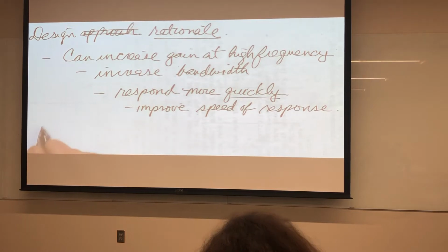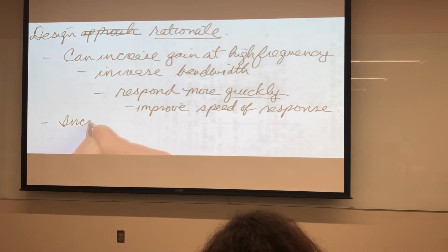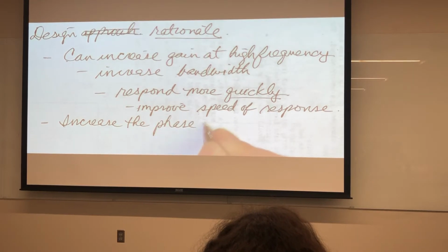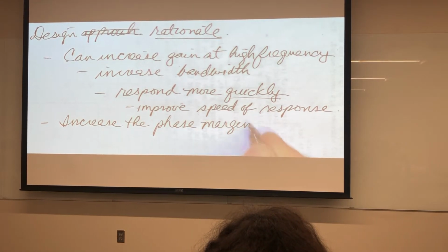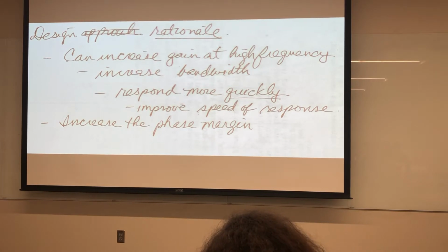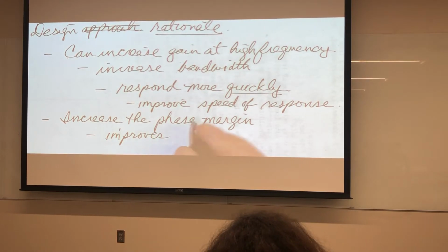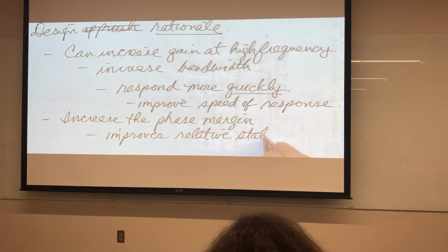The other reason we use a phase lead is we can increase the phase margin. And that basically helps us, it improves what we call the relative stability.